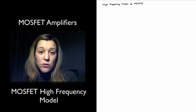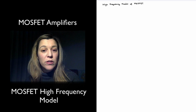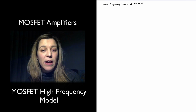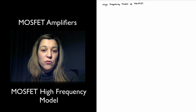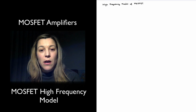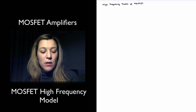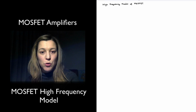The one thing we can do is, if we have a particular MOSFET which does not meet the specifications, meaning it will give us too low of a high cutoff frequency or too low of a bandwidth for our amplifier, we can select a different MOSFET transistor, talking in discrete circuit design, that may have better high frequency characteristics. But in most cases, we're just going to be estimating what the high frequency response will be.